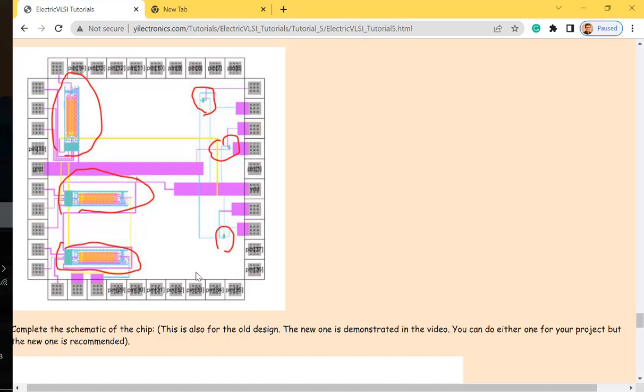The one we are using for my senior design right now is 180 nanometer technology, which means the smallest transistor length you can fabricate into the wafer is 180 nanometer. These ones are 600 nanometer for each transistor, which is 40, 50-year-old technology, but the 180 is a 2005 technology. Used to be super good and popular. Right now, it's still one of the most popular technologies being used. Doesn't mean it's the best performance, but just because it's very cost effective, it's cheap to fabricate, and it's not that big, not that small. It's just okay, all right? Still the most popular one, the one we are using right now.